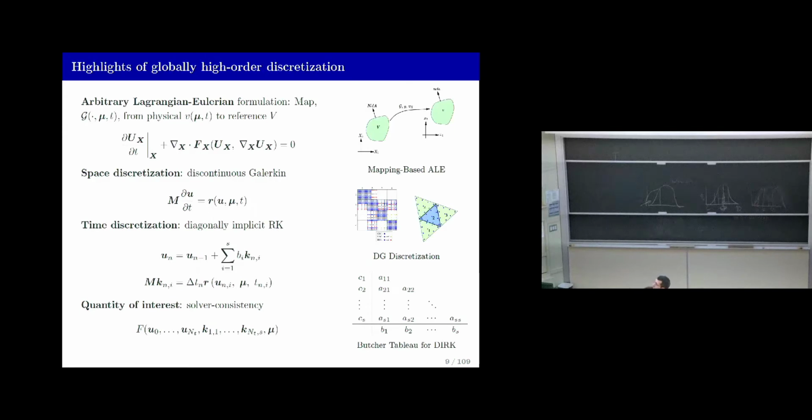So first thing we're going to do is we want to be very general. So I want to possibly be handling moving and deforming domains. Think back to that flapping wing problem. Your entire domain is moving, deforming, it's parameterized. It can be a real mess to handle. So instead of working on our physical domain, we map to a reference domain. People that are in my finite element class, this is very similar to this isoparametric concept that we've been talking about recently.